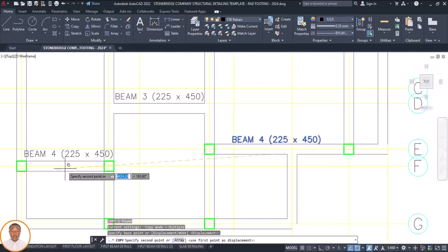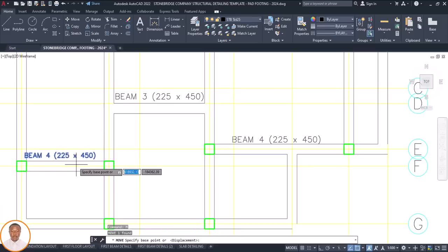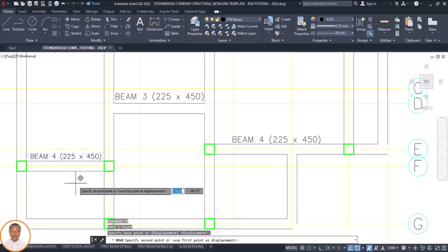Is that okay? Here. Okay, this text is big. A little bit big. Let me see if I can scale it down. Scale, enter. At this point, 0.8, enter. Okay, it's okay. Then I'll press on M, enter. So can you see it now? So do you see it?